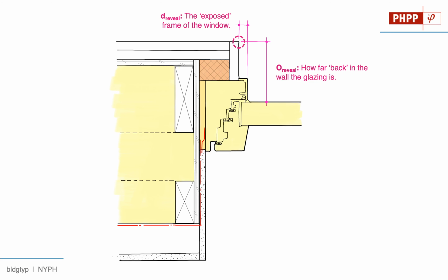As we talked about in previous lessons, we stopped the wall model back at the sheathing when we were assessing R value. In this case, we're not concerned with the thermal boundary. What we're concerned with is the physical boundary with the outermost shading object, the outermost physical element that could cause some shading. We measure from that back to the glazing surface itself, the outermost pane of the glazing.